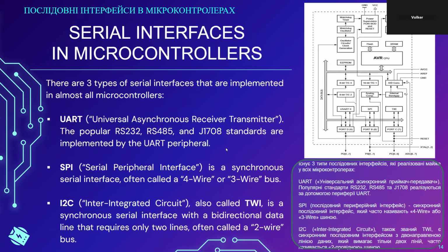Okay, now I am focusing on the serial buses in microcontrollers. I have an image to the right here. This is actually taken from the microcontroller that is sitting in one of the more popular, smaller microcontroller boards. It's an Arduino board. Hobbyists probably have heard of the Arduino boards. It's an 8-bit, kind of an obsolescent 8-bit CPU. But I picked this image because in the lower half or lower third of this image, you can see the USART, the SPI, and the TWI.